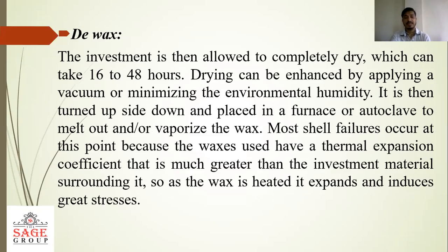Dewax. The investment is then allowed to completely dry, which can take 16 to 48 hours. Drying can be enhanced by applying a vacuum or minimizing the environmental humidity. It is then turned upside down and placed in a furnace to melt out or vaporize the wax.